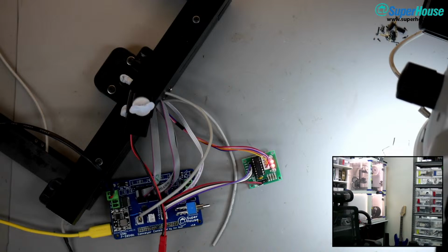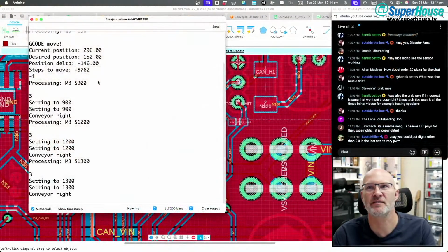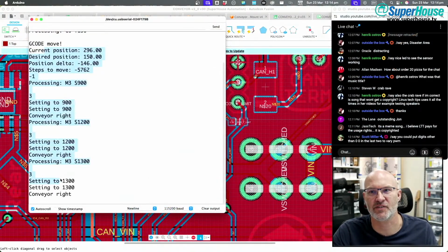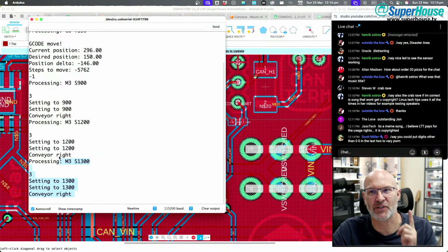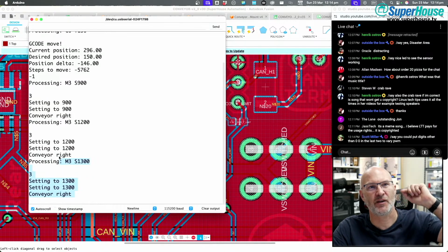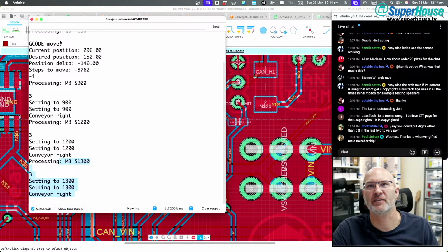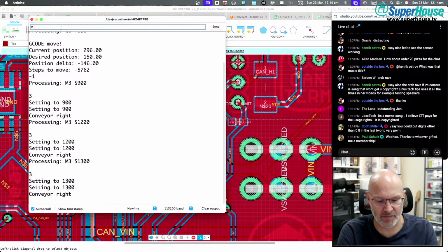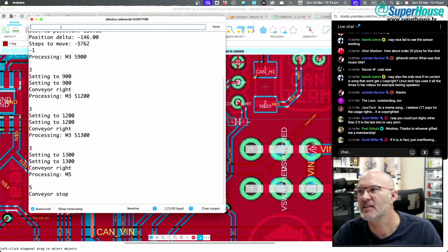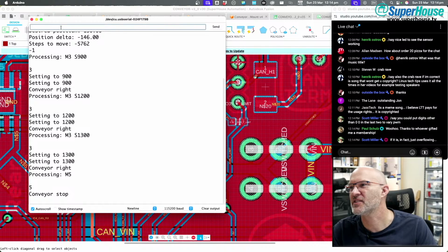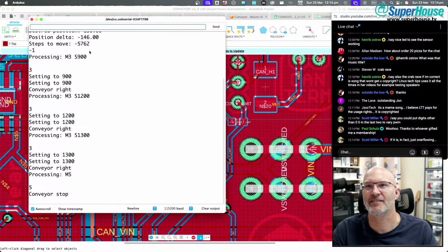Yeah, but what I want to do is do some motor tuning now. So that, step one, I need to make sure I've actually got the correct motor. I need to put a 120 RPM. Hang on, I'm going to stop this now. So if I do an M5, it should stop. Yep, you would have heard it stop. So it is in fact just overflowing. Yeah, the value is not making sense.